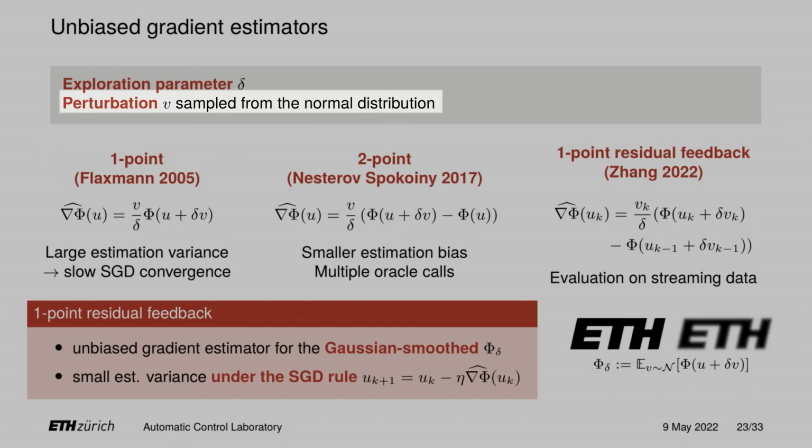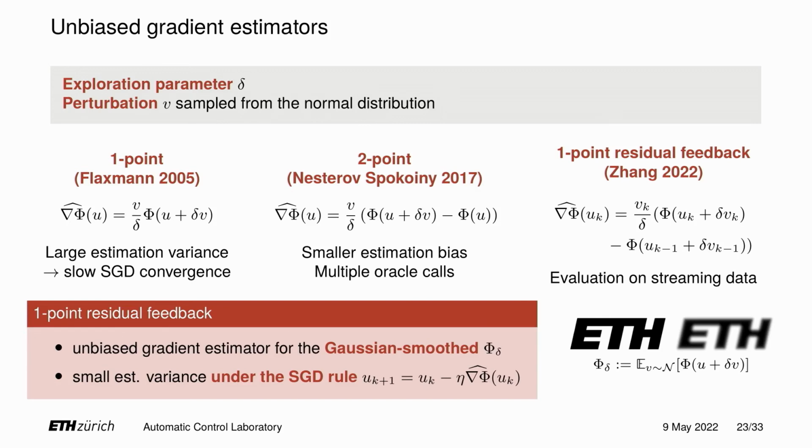So that you can exchange some slack with the exploration. If there's an input constraint that you're not aware of, and that is taken care of by the physical system, like you send a set point and it's tracked up to some level, and then is not tracked anymore above some limit, saturation, that's actually not a problem, in the sense that we allow non-smooth cost functions. That would just be an H, not smooth H. So that would actually be an input-output function, which is saturated there.